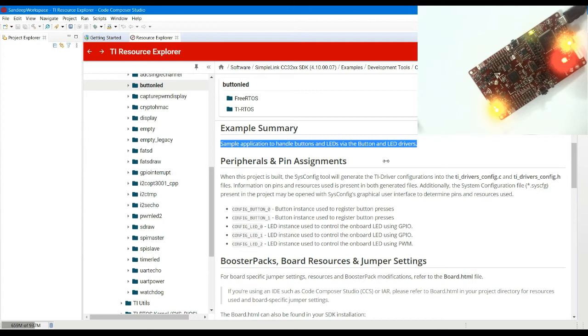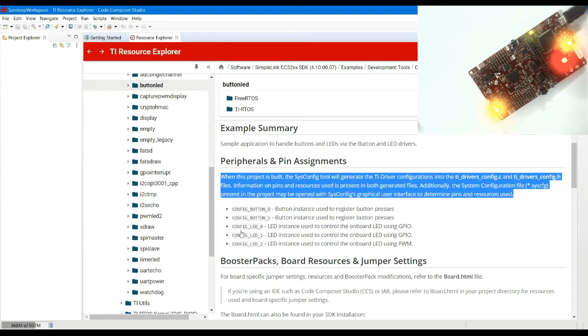So as I told you, buttons in RTOS are treated as button objects. So we will be creating some button objects, and we also have onboard LEDs. We have 3 onboard LEDs, so we can create some LED objects using the LED drivers. And after that, it will be only a simple task to detect the condition of the buttons, and accordingly pass it on to the LED handle, and do whatever we want to do with the LEDs. So you can come a little bit down. For the time being, you can just ignore whatever they are saying over here.